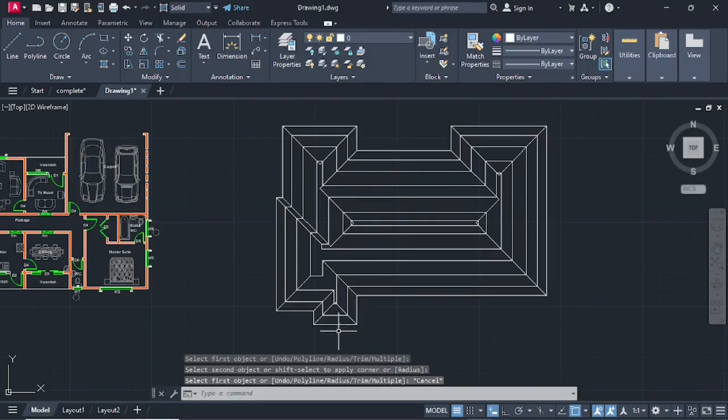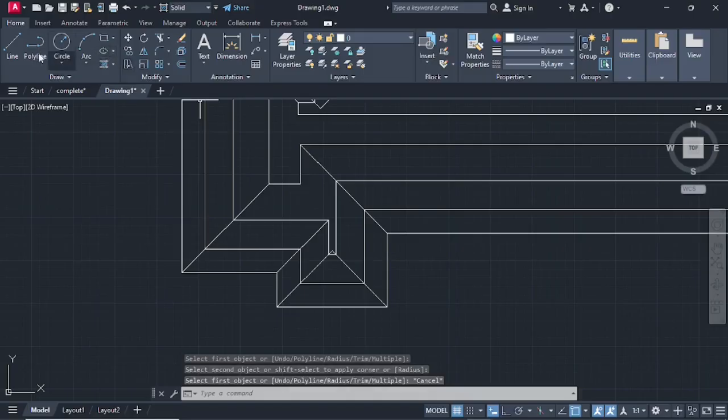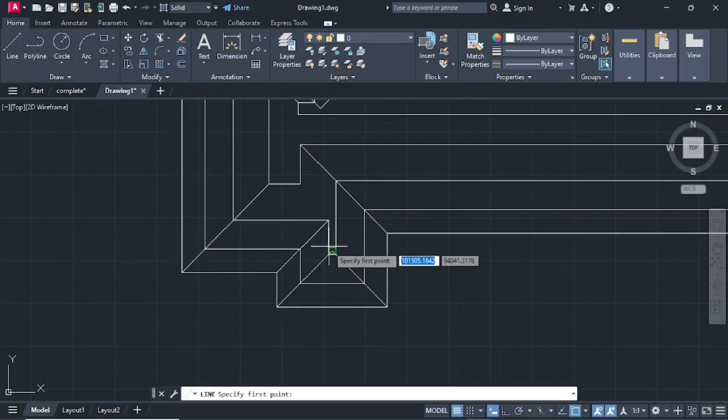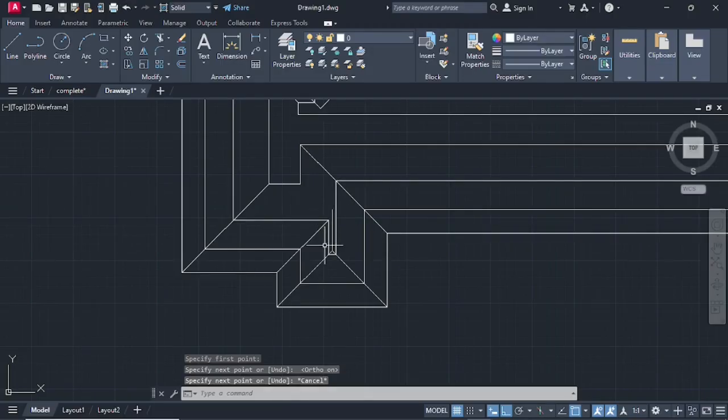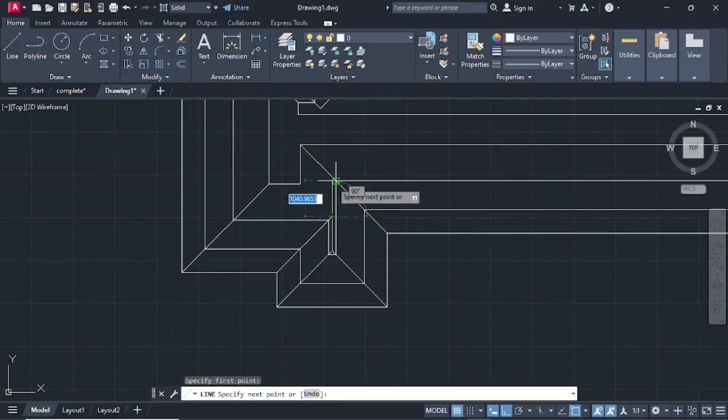Then I'll go on escape. Here I'll make a line like that, going up. Then on the auto mode, in order to draw a straight line like that, I'll press on escape, then type in F for fillet, press on enter. I'll connect this line and that line, press on enter. Then here I'll need a line. So this line here should be parallel to this other line over there.